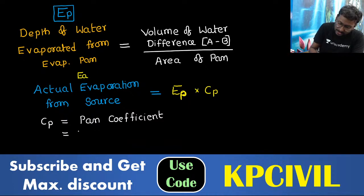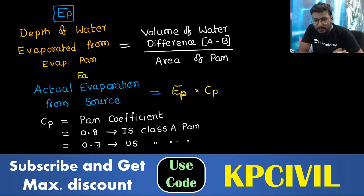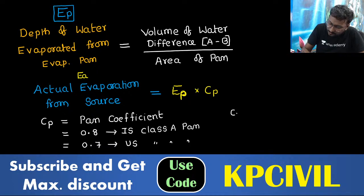Now, pan coefficient is equal to 0.8 for IS class A pan. If you are using Indian standard class A pan, pan coefficient is 0.8, and 0.7 you can take if you are using US class A pan. Clear? If you are using Indian standard class A pan 0.8, US class A pan you can take pan coefficient 0.7.